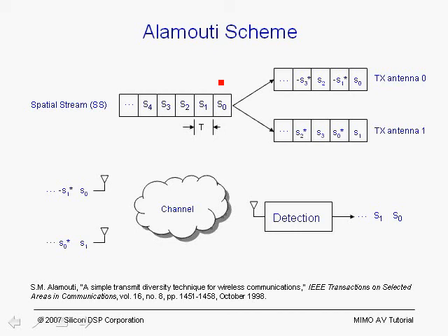So that's a key point to remember in the derivation of the Alamouti scheme. So consider S0 and S1 to be carriers within the OFDM symbols, and they are delayed by t seconds, which in our case is 4 microseconds for an example OFDM system based on 802.11a. Now, if we were going to add the Alamouti scheme for transmit diversity to 802.11a, we would have to break the standard, as we shall show, in terms of the detection at the receiver side. But as we discussed with cyclic delay diversity, we can actually add transmit diversity in 802.11a without breaking the receiver.